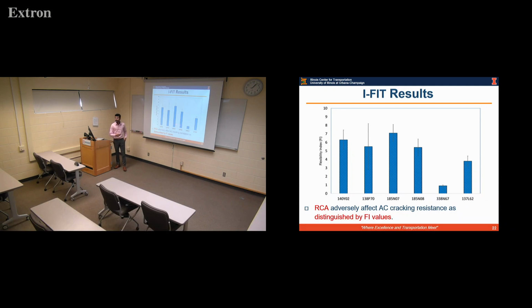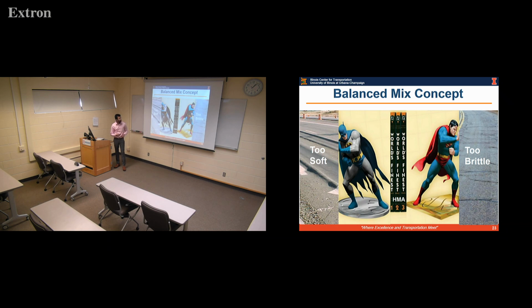All of the mixes are stiffer and fall below the 8 threshold, but they are better than if we have RCA in them. So in order to put these things together, we need a mix which can perform both for cracking as well as for rutting.